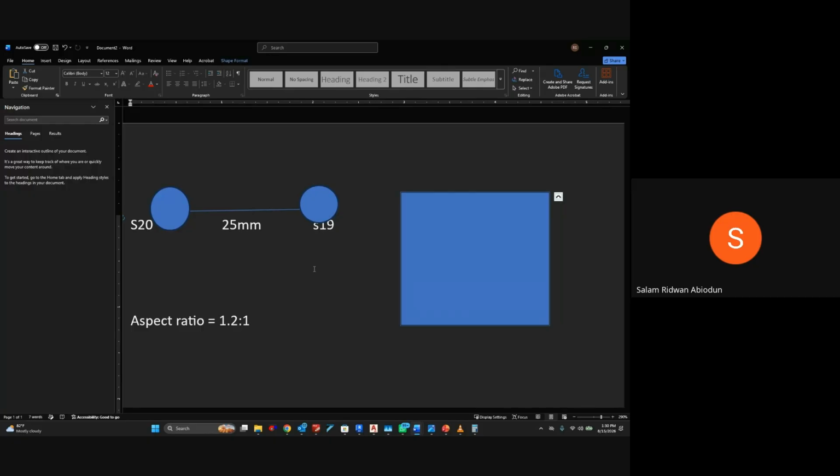But in our maximum area of operation, do you know what it means? It means that all those sprinklers we are considering are working at the same time, which is very rare. Because we normally consider worst case scenarios. How many sprinklers did you map out in that place? 4. Is it not 4?